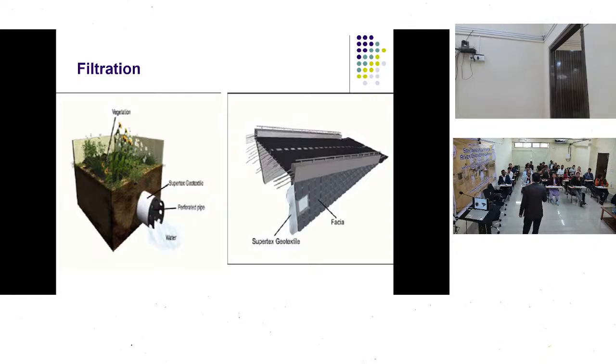Suppose I have a non-woven geotextile having an opening size of maybe more than 5 microns. Now, clay particle sizes, as we have studied, are less than 2 microns. So what will happen? The clay particles will start migrating out through my non-woven geotextile. This means if I want to use this non-woven geotextile in conjunction with clay soil, I need to provide another layer of protection between the clay and the non-woven type.